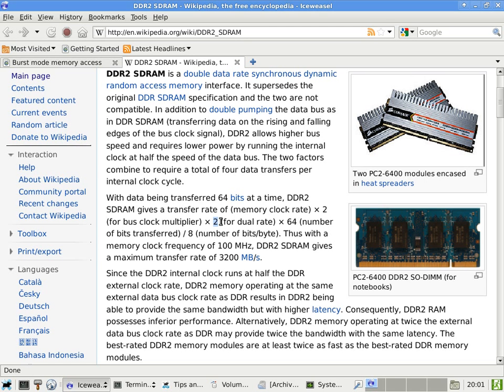Now with DDR3, if I understand correctly, it will also sample between the transitions. So this will also be a time to sample, this will be a time to sample, this will be a time to sample, this will be a time to sample. So that's why we can. It would sample in the corners. So DDR4 would sample in the corners. It gets incrementally difficult because